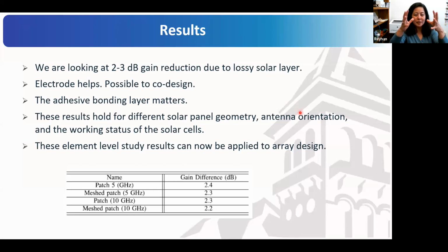And of course, you might say, hey, the antennas oftentimes should be talking to the ground. That is true. But for CubeSats, even the bottom of the satellites are placed with solar cells, because when you first launch it, it will be tumbling. During tumbling, you need to make sure you get sunlight from every direction. And therefore, again, transparent antenna is still important for that application.